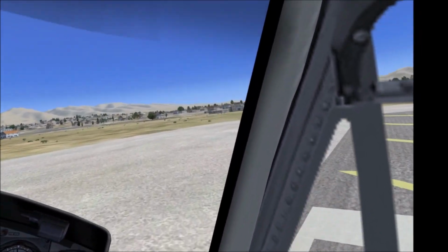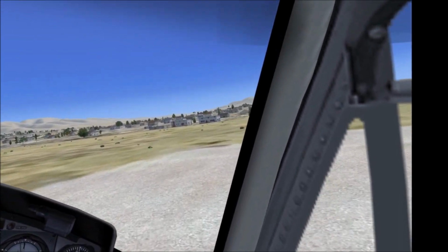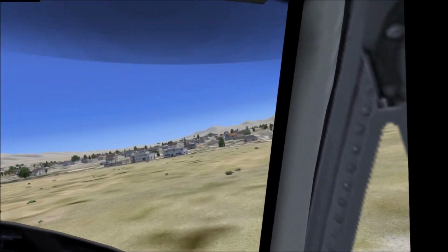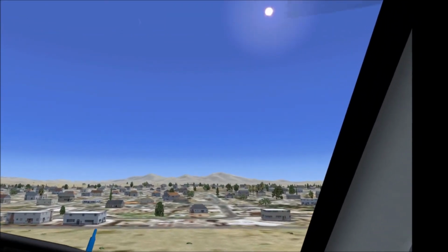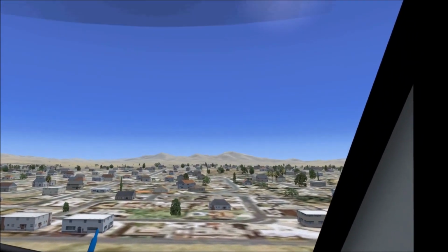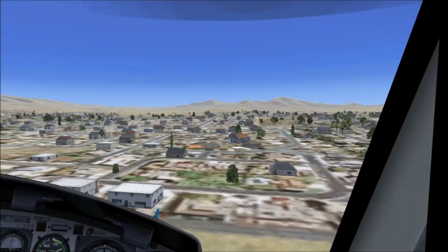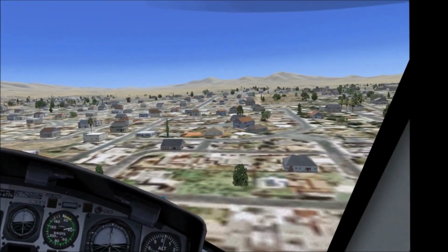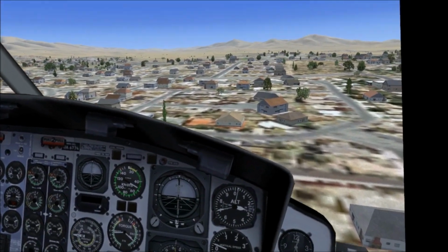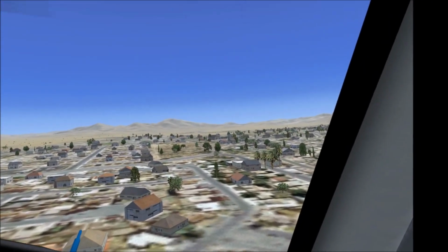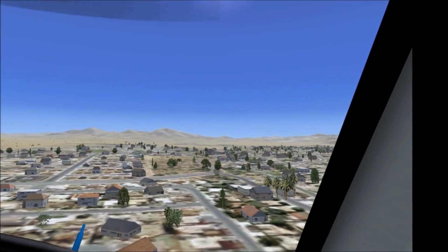We're going to test some more here in cruise flight. So can't get points for that, but we do have some more things to look at. We also should have seen some RPM changes. I mean, governors are good, but we should have seen the governor kick in and try to maintain that rotor RPM. So that's kind of a, can't really give points for that one either.